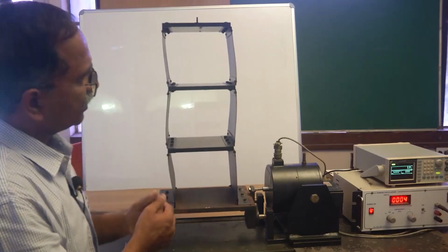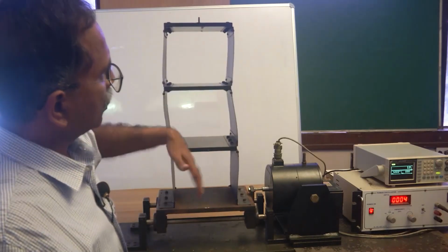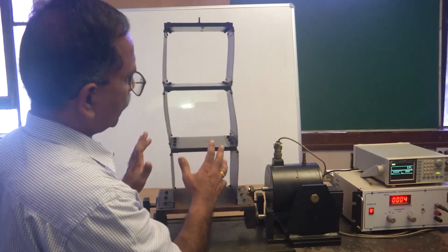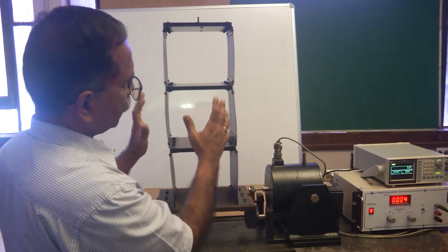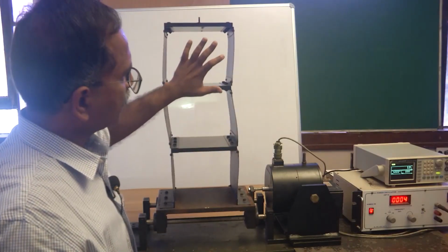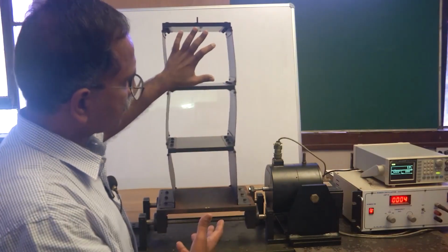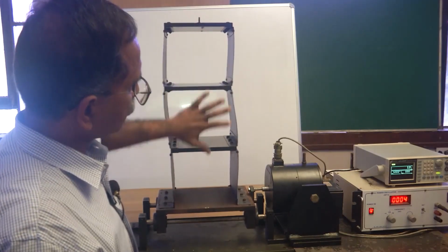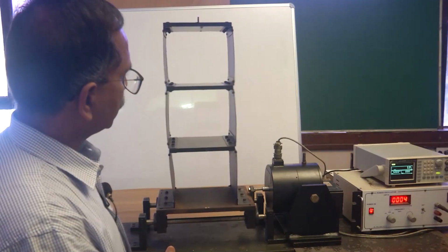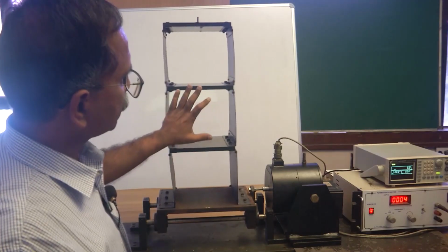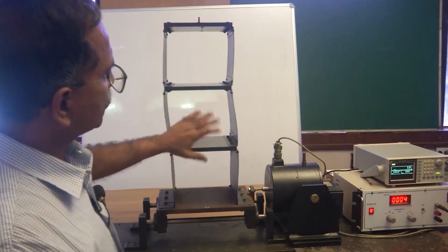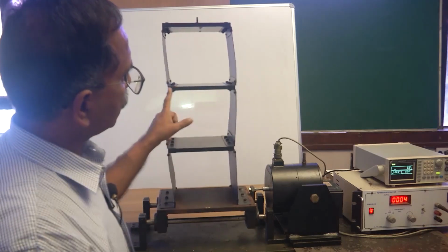So one node gets added in general when you go to a higher mode of vibration. So again, this is a resonance. This is not strictly theoretically a mode shape, but the operation deflection shape, or the displacement pattern of this multi-degree of freedom system when it vibrates at its resonance, is actually representing the mode shape corresponding to that natural frequency. So 5.9 hertz is what we have observed, a major resonance here, the third natural frequency related resonance, and at that resonance this executes largest amplitude.